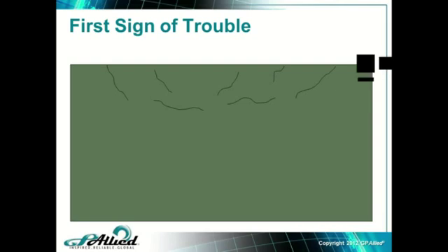So it starts deep in the root, if you will, not all the way in the root, but on the back side of that curve, and then the two curves match, and then it comes out the other side. So if you could look at the gear tooth profile and see the fat portion of the tooth, inside to out, it's the fat portion where rolling contact fatigue will occur.